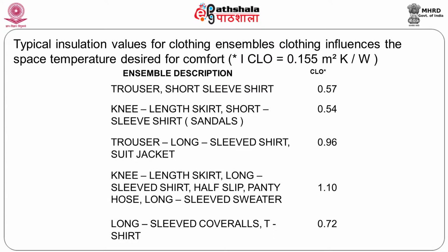Now comfort is also influenced by the type of clothing one wears. In summer you find people deriving comfort in non-air conditioned areas by knowingly or unknowingly shedding clothes. By shedding clothes, I do not mean somebody putting on a bikini. I mean somebody, instead of putting on a pant and shirt, putting on a lungi and a banian. Now there the clothing level has reduced, which means the insulation between the outside heat and the inside heat, meaning my body, has reduced and I can be comfortable at slightly higher temperatures.